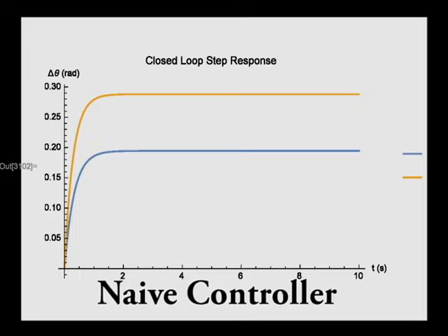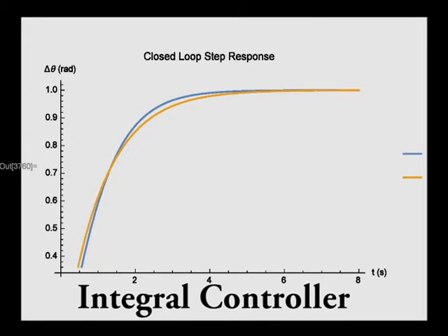And therefore, we introduce this absolute term, which is the sustained displacement from the reference point, which is effectively the integral term that corresponds to a PID controller. This is in fact analogous to a PD controller for the former case, and in the latter case, a PID controller, in which the introduction of the integral term effectively mitigates the steady-state error.